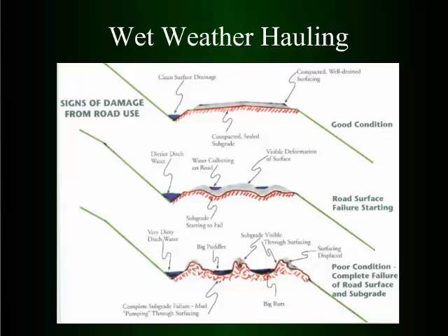And a lot of this, it may well be that this ditch is not carrying water off well enough, and so you're saturating this whole grade. I'm not sure if that was the intended function of the diagram or not, but a lot of times if you see a full ditch, you'll see ruts in the road adjacent to it. And that means generally because your subgrade is saturated.